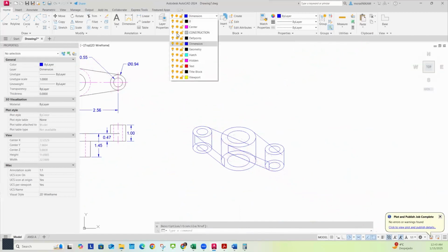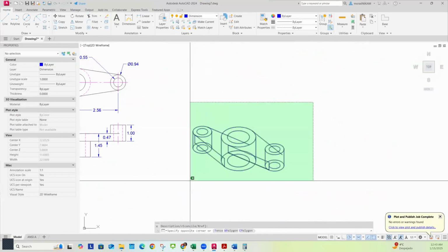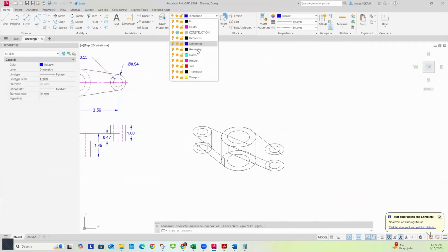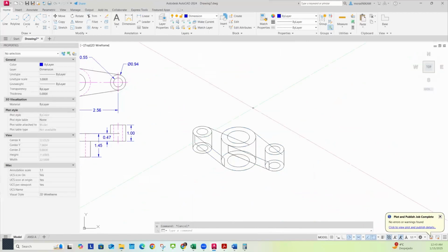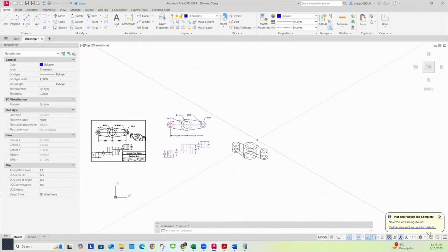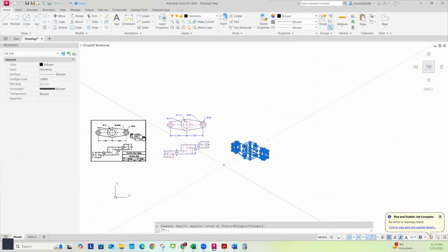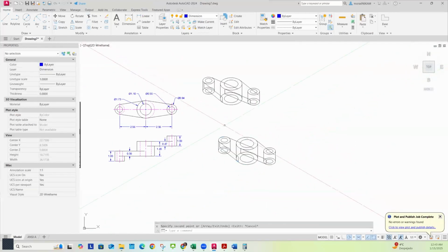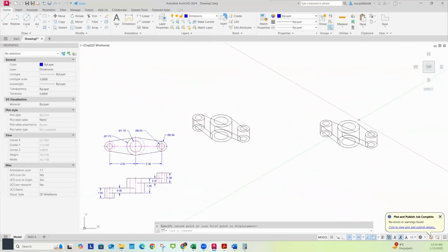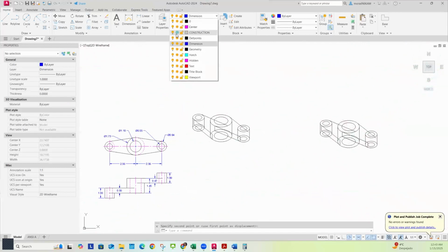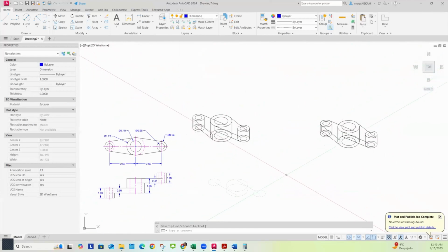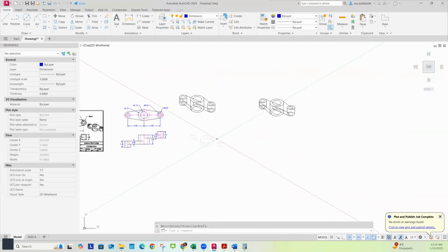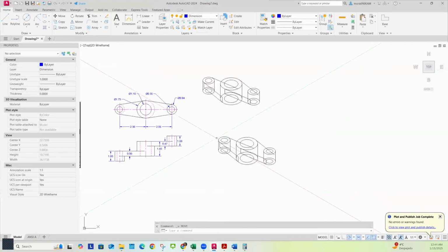And then I'm going to freeze the construction layers. I'm going to grab all this, put it on the geometry layer, and then I'm going to copy it because it took me a while to make this, and once I trim it, I can't really get it back very easily. So this way I have a copy over here in case I mess up. So I'll unfreeze the construction layer. And I'm realizing now that I didn't bring my line work with me. So let me undo that for a second.